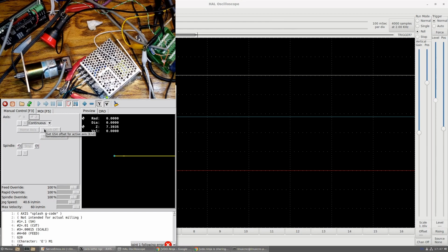With a stepper, you stall it, you have to rehome it, or you have to figure out your home again. That's what's really awesome about this type of setup. Granted, a Mesa card or Mesa hardware or whatever other hardware out there, I use Mesa, it works really well. Whatever you're using that does this closed loop within Linux CNC, it's awesome. It works very well.